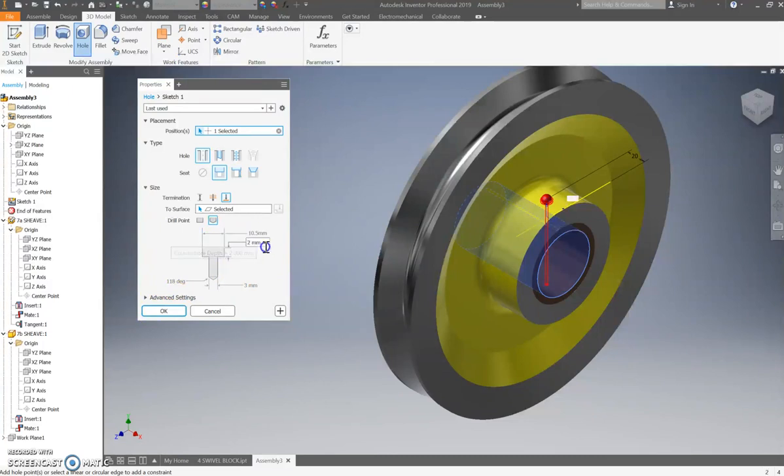Depth of the counterbore is 10 millimeters. 10 deep. Oh, I did that thing again, didn't I? 10 with an extra M for, caps locks on, millimeters. And then the remainder of the hole, if we select this one down here, is going to be 5 millimeters in diameter. 5.